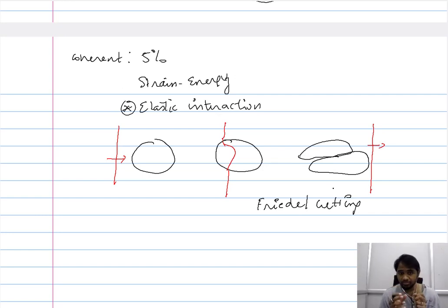Now thirdly, we saw when we allow the dislocations to interact with the particle, the driving force is considerably reduced, and therefore the dislocation cannot move as easily as in case of the homogeneous material. So even though this ties up to restricting the mobility of the dislocations, it is achieved by reducing the driving force, because of the interaction between the whole particle and the dislocation. So this is a way a coherent particle enhances the creep resistance as a whole.